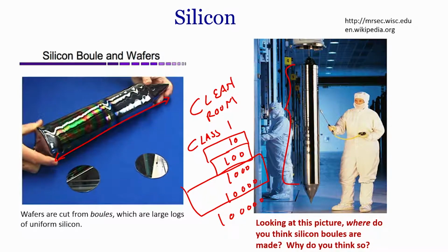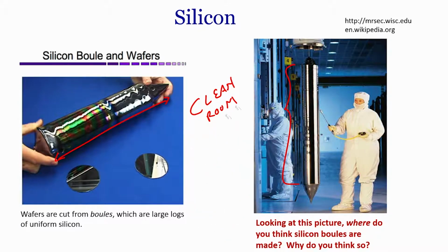But the second question is, why do we think so? The requirement of the clean room is to avoid any impurities. If the class is 1 or 10 or 100, the room is much cleaner, and fewer impurities are present compared to rooms which are not clean. We want our silicon wafer to not be doped with impurities, because even one small single impurity of 0.5 micron will kill your entire chip.